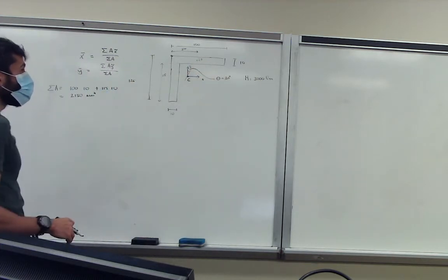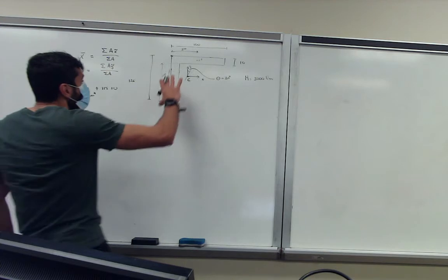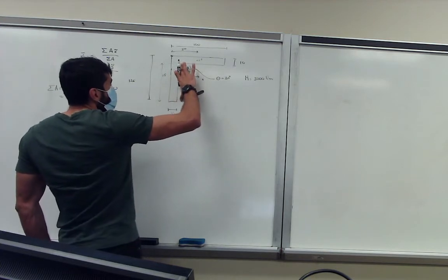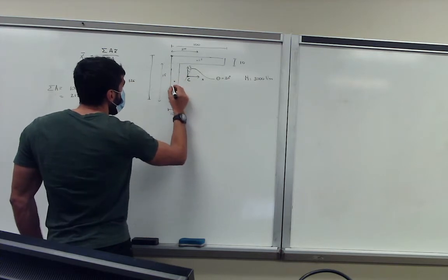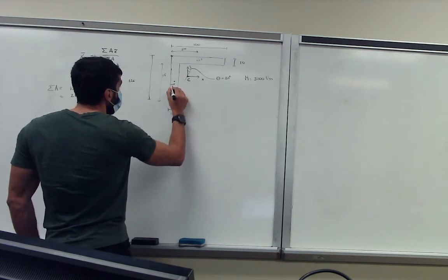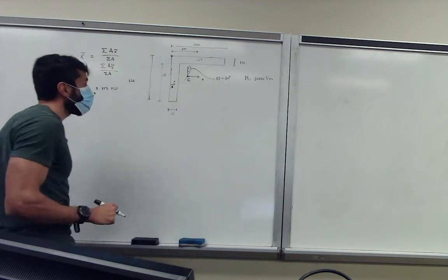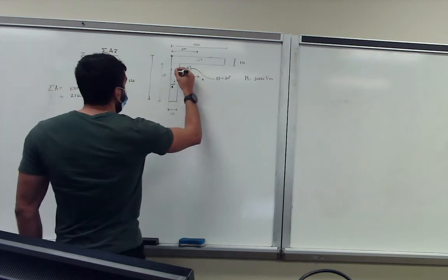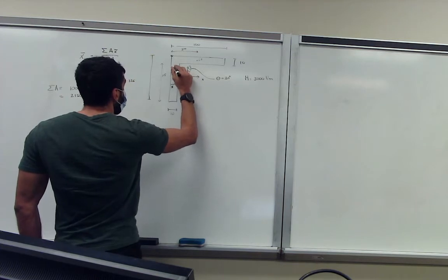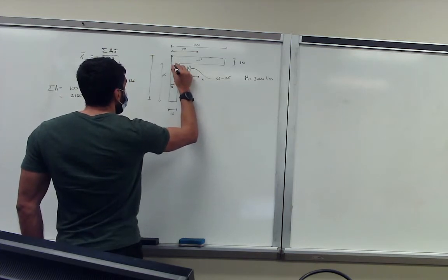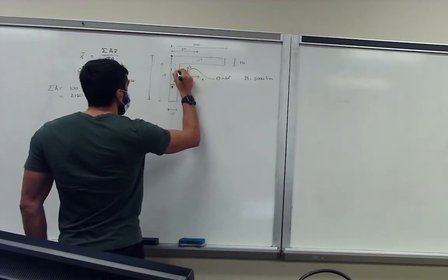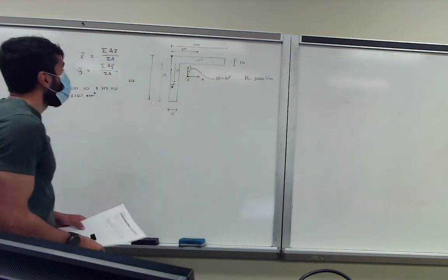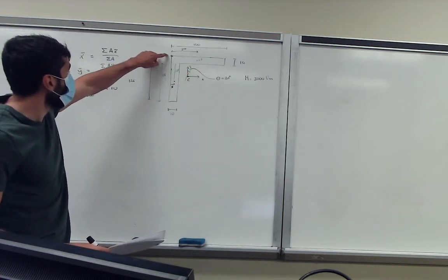Now we can draw the same thing for our vertical flange. We're thinking about this axis here, so the 115, not the 125, lies in the middle, of course. Again, this part will be 5, just a coincidence since both of them are equal thickness, and the wide part will be 115 over 2, so 57.5. That's from this part, not from the total part.